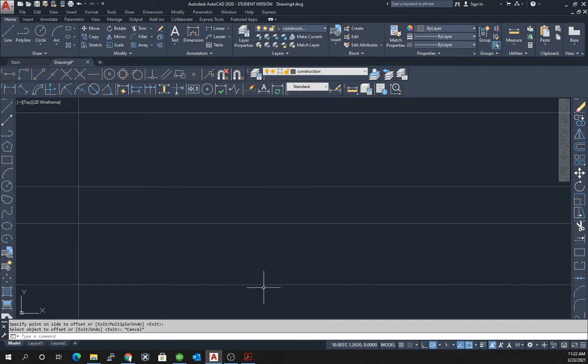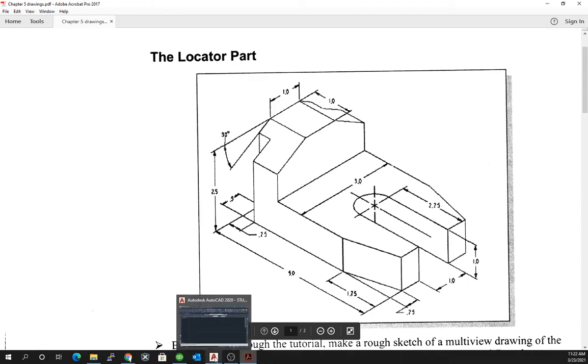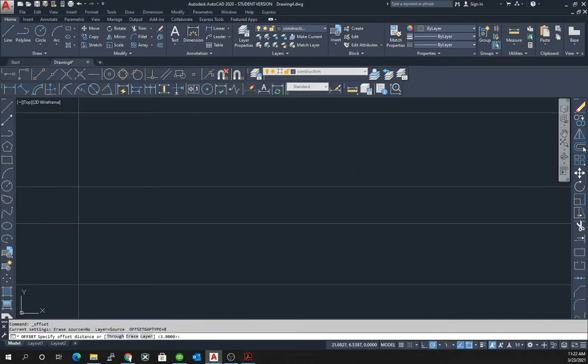And back from this corner now we need to make some vertical lines. So the length of this part in the X space was 5 inches. Type 5, choose my line, put my offset in. We'll put another spacing of 1.5 inches in to put a separation in.